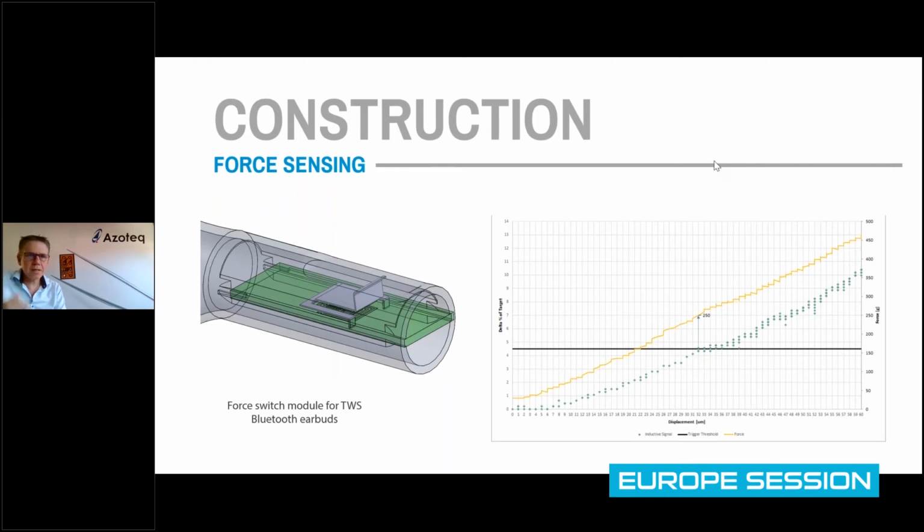Yeah, I understand your question. Firstly, inductive sensing is more forgiving compared to capacitive sensing, so a little bit easier in that sense. Also, the inductive fields are much better controlled since they are located in the area of the coil, whereas with capacitive sensing, your whole sensing trace is exposed and often sensitive to interferences.